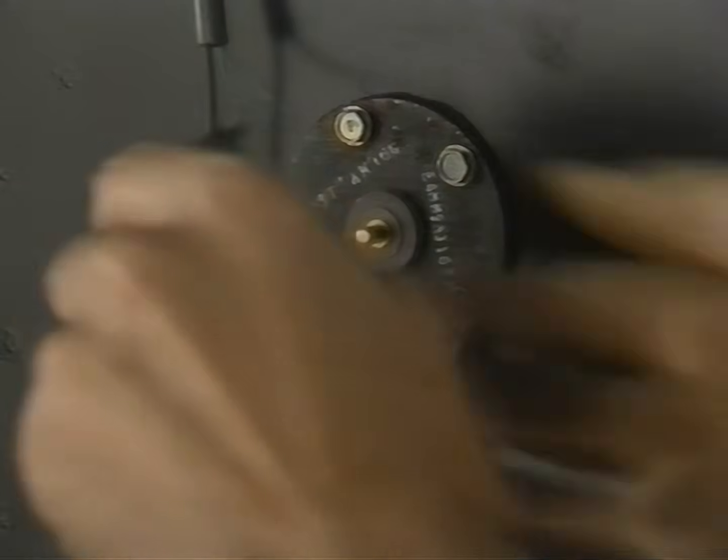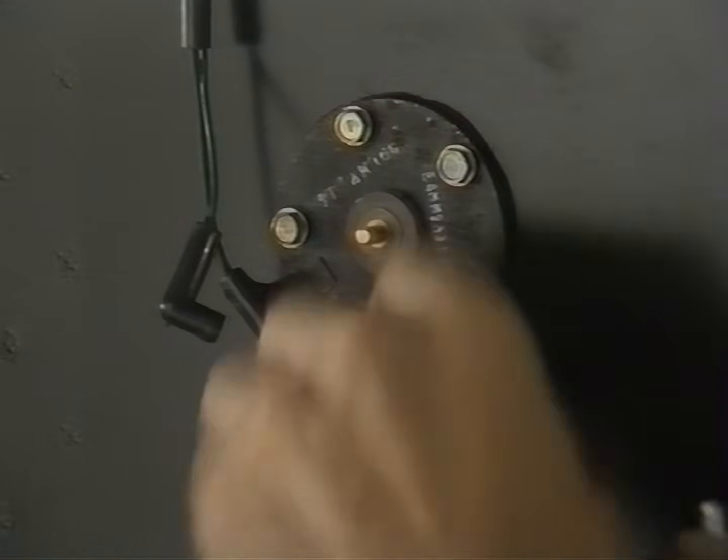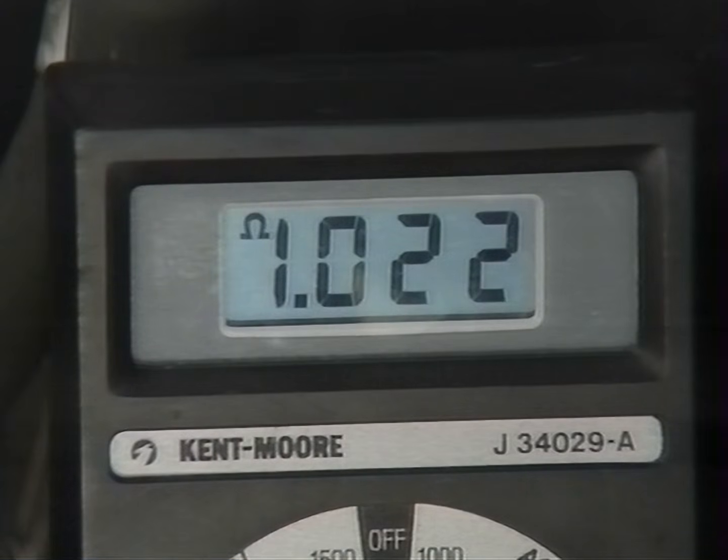You'll need to continue troubleshooting by checking the resistance between the fuel level sender terminals. If the resistance is close to the specification for the amount of fuel in the tank, the sender unit is working properly, and the cause of the open is probably in the sender ground. If the resistance reading does not coincide with the amount of fuel in the tank, the sender should be replaced.